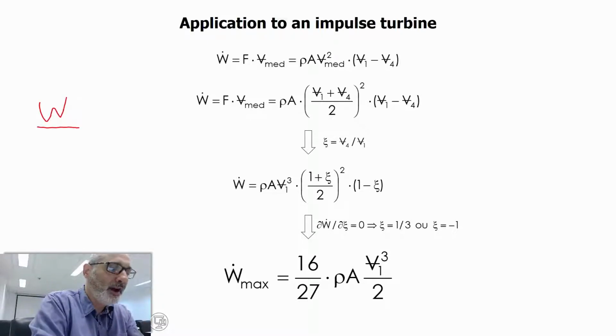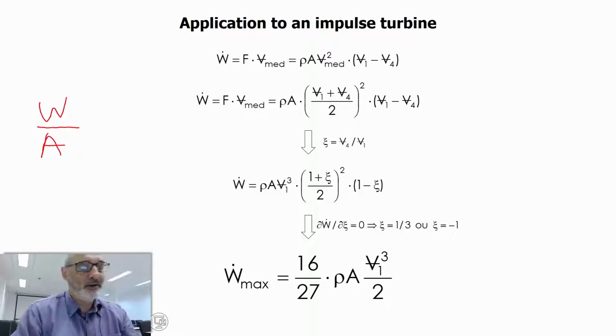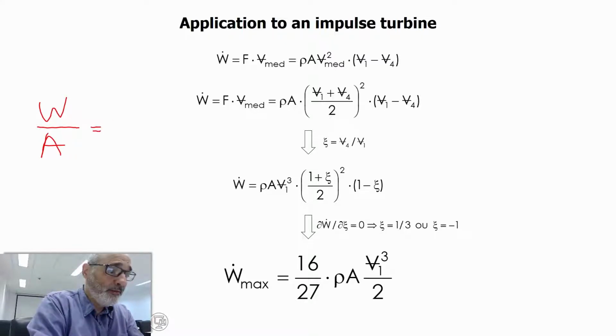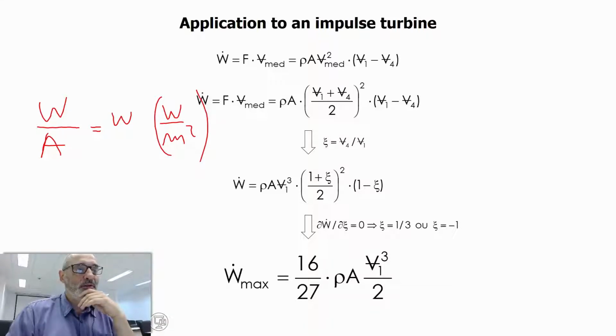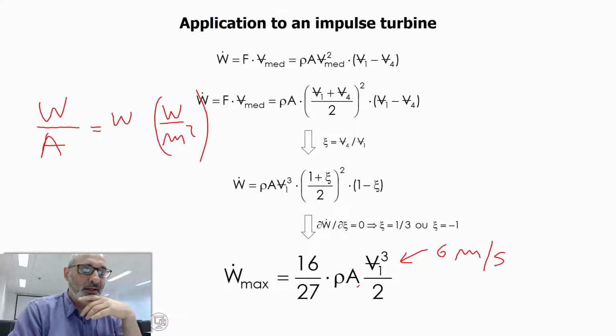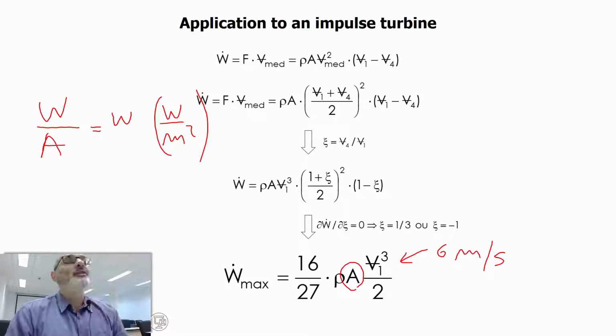If you divide by the area of your windmill, you have small w, in watts per square meter, and that's the potential density of the wind. So if you want to generate, say, 1 gigawatt of electricity from wind, and your wind is 6 meters per second in that particular place, you can use these numbers to calculate the amount of area that you're going to need.